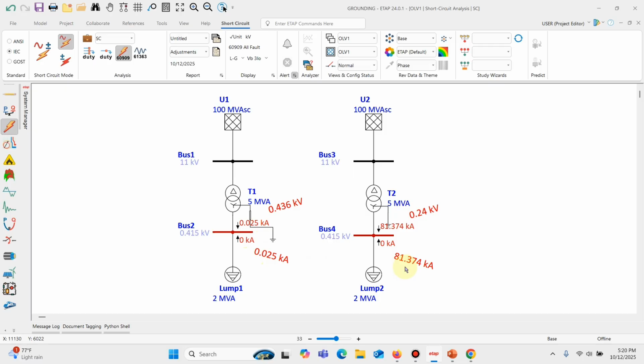So imagine in your system, let's assume in the actual power system, in reality, it is grounded through a resistor, and in your modeling and analysis, you actually carry out the grounding as default solid grounding. So it means that it will affect all your results. Your short circuit results are affected, your relay coordination results are affected, your arc flash results are affected because the magnitude of incident energy is relative to the magnitude of short circuit current at that location.